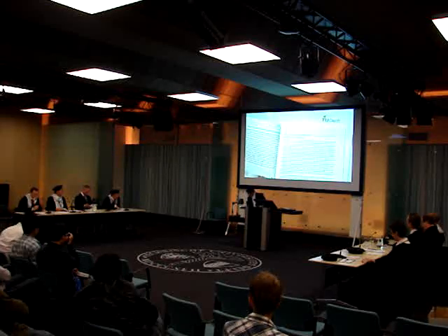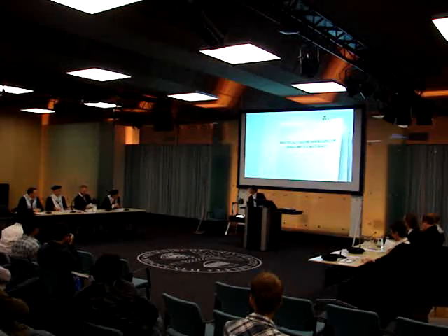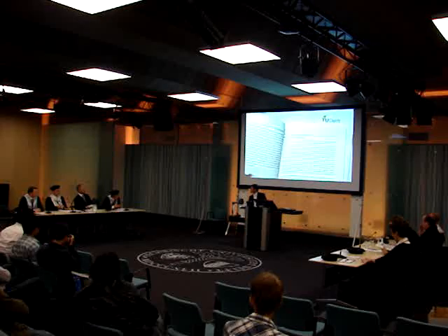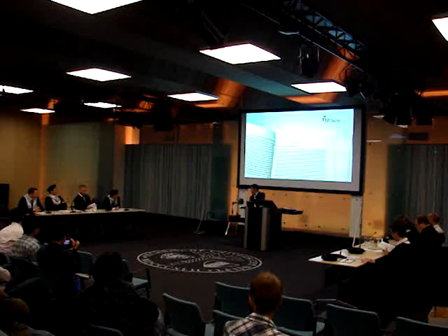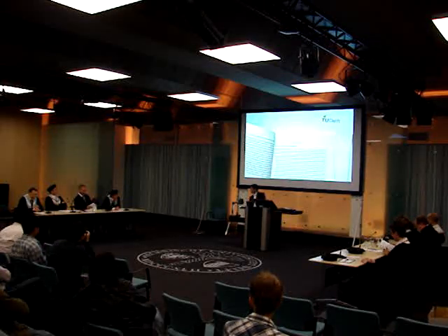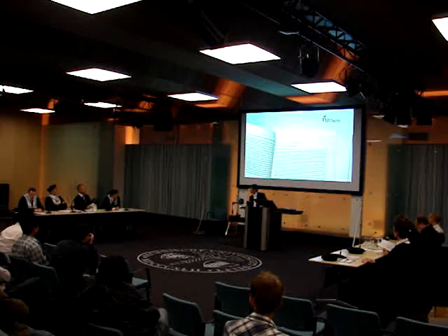But what is the physical meaning, let's first take these three, kappa, gamma and beta? They sound to me a bit abstract, they refer to a curve. Are they somehow related to the fracture energy? Yeah, it's related to the fracture energy because these parameters define the softening curve and the area of that curve is the fracture energy, so it's related.